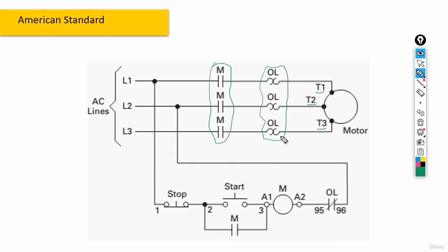And we also have a control circuit here. First off, the control circuit is being fed by 2 of the phase lines, for example, here by L1 and L2. And also, guys, another thing that might actually catch your eye would be the order of setting the equipment. If I want to elaborate here, the order is actually different from what we used to see in the IEC standard.